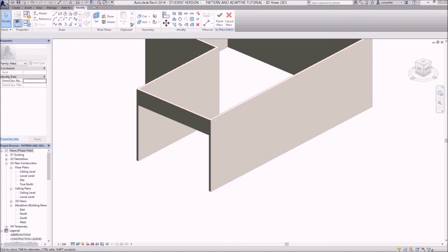And then I could click on this and edit it again. So this is the mass that's showing up. If I edit that in place, I could then find the divided surface, which is that truss, and open up down here, and I've now got a different type. I've got frame 50 brace 20, so I can click on that and it thins everything up for us.